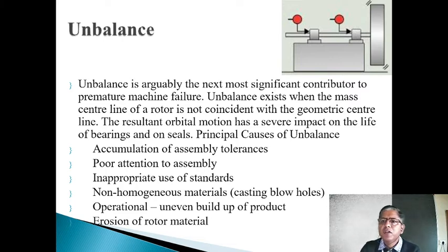And if the rotor width is substantial with respect to the diameter of the rotor, then such unbalance requires multi-plane balancing, because a lot of couple is generated apart from the centrifugal forces. The couple is also generated, and that is why such problems are to be tackled as multi-plane balancing problems.